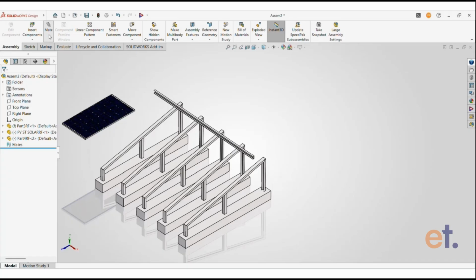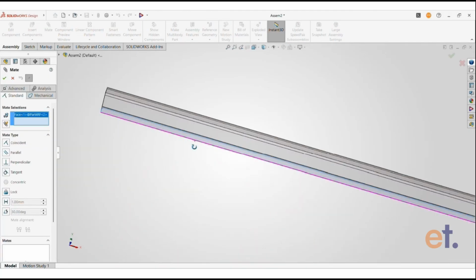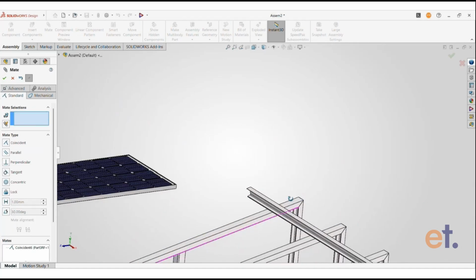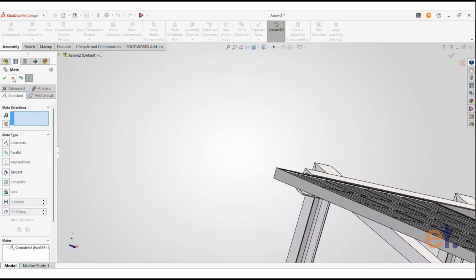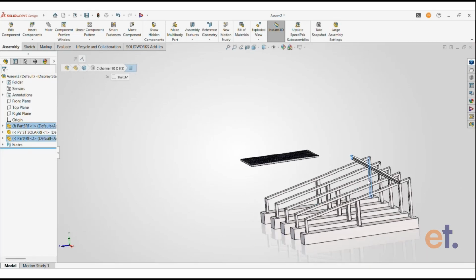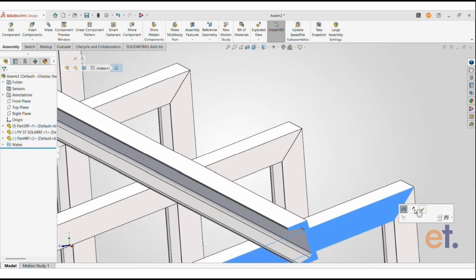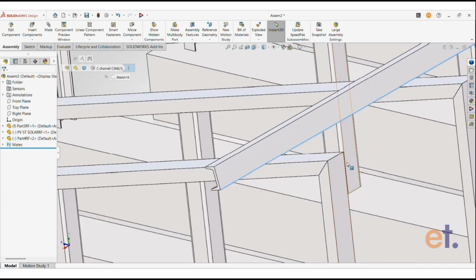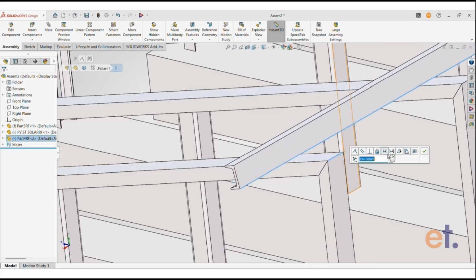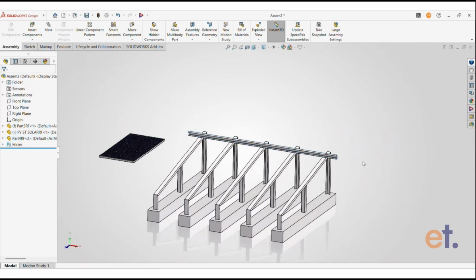Now, as I inserted multiple components of my assembly, I can give constraints to each and every part of mine with the help of SolidWorks Mates. Here, whenever we select any face in SolidWorks, it will automatically prompt you which mate is applicable here. As you can see, I have selected multiple faces and it has recommended me this particular mate. SolidWorks automatically recognizes what features you are trying to apply while constructing it. So if it is not applicable, it will not recommend it.